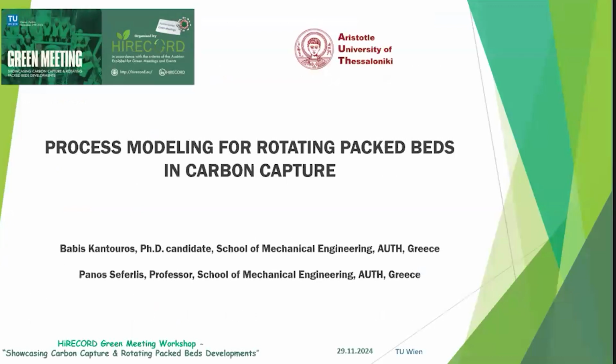In this presentation, we will explore why process modeling is essential in advancing CO2 capture technology, focusing on rotating packed beds, also known as RPBs. I will walk you through the development, validation, and operational analysis of a custom model, focusing on the use of amines as the solvent.